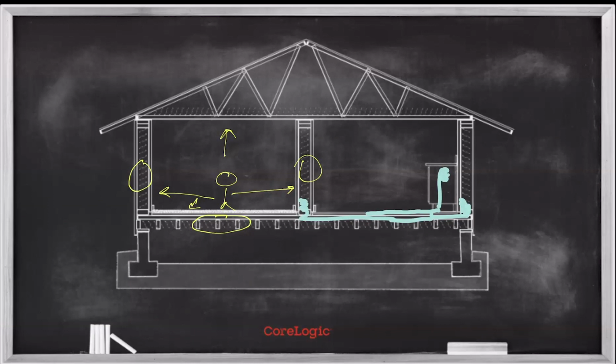And the principle that I always stress in helping a technician really ask that question honestly and sincerely and get to the root of the answer is to not think of what you're seeing in a building as assemblies. You got to think about the individual components, right? A common mistake that a lot of us will make, just the human mind simplifying things, is that when I look at a wall, I call it a wall. That's the habit you've got to break as a restorer.